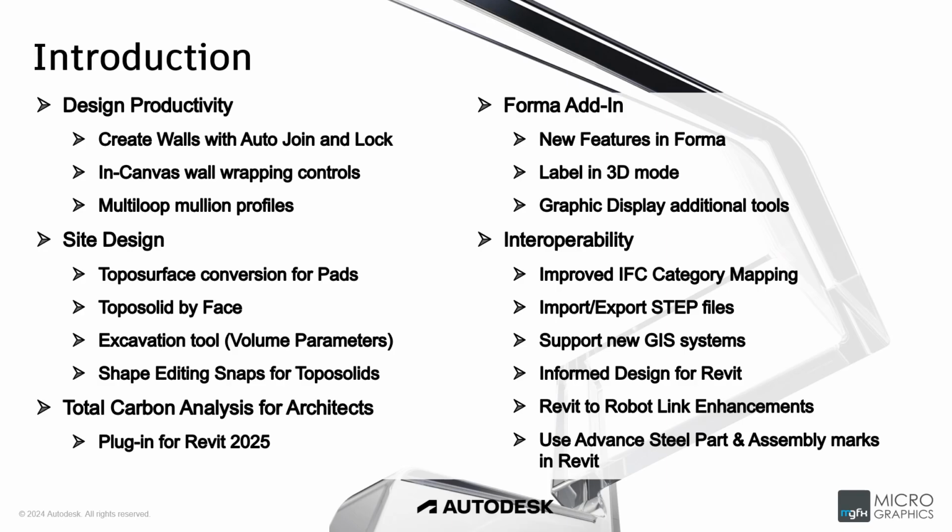Next would be site design. In site design, I only selected the topo surface and topo solid, the conversion for pads to 2025, then topo solid by face, then the excavation tool, which now offers us volume parameters for the cut and fill, and then shape editing snaps for topo solids.